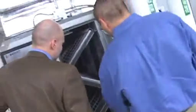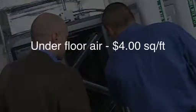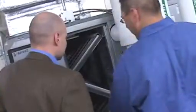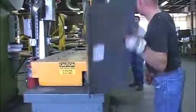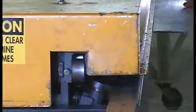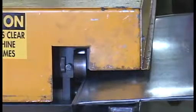The initial cost savings when installing underfloor air are benefits important to every job we plan. When we exclude the capital cost of the equipment, we've experienced underfloor air numbers of $4 per square foot. We've all seen ducted overhead systems come in at $7 per square foot and more. These savings come from a number of factors. As you can imagine, there are substantial savings to be found regarding ductwork costs. The material and labor to fabricate the ductwork in overhead mixing systems is considerable.